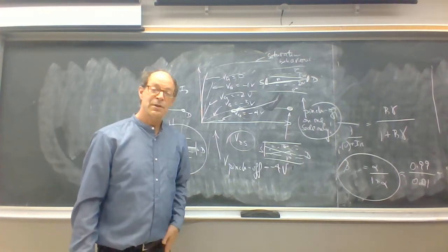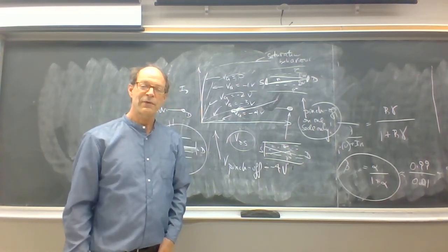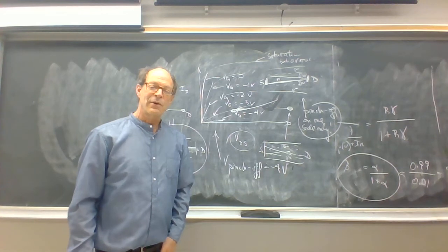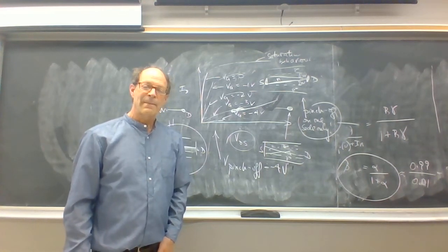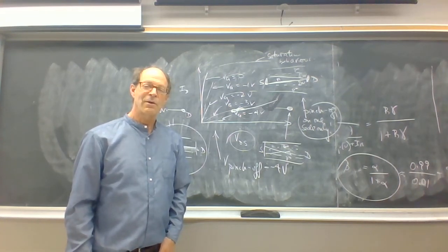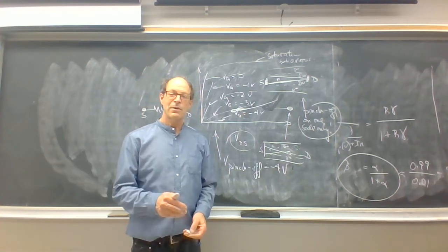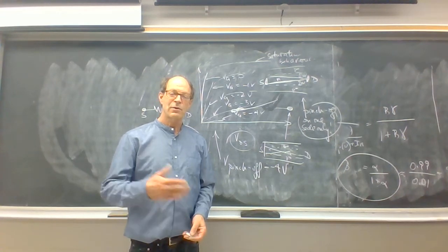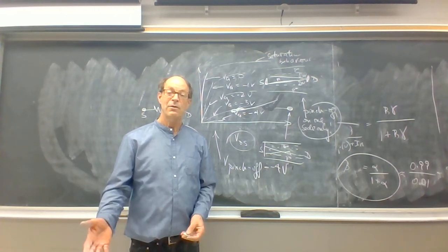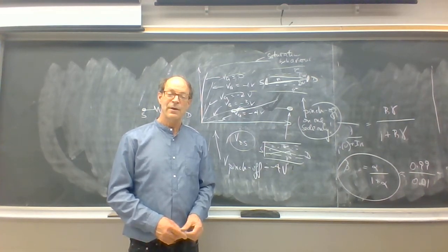And the question is, what's the real significance of a junction field effect transistor compared to a bipolar junction transistor? First of all, the junction field effect transistor has an important advantage. It has essentially zero gate current. If you remember, in the bipolar junction transistor, the current flowing into the base could give rise to a collector current, which was perhaps 100 times bigger than the base current. Whereas in the junction field effect transistor, there is virtually no current flowing into the gate.